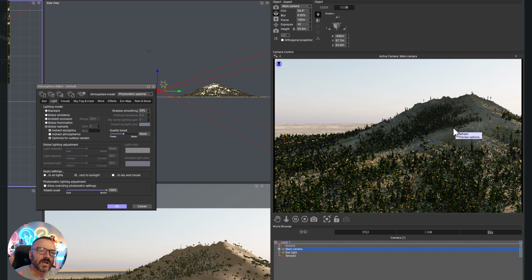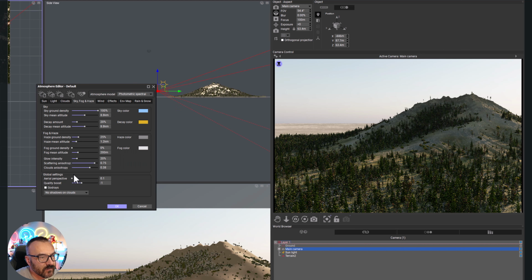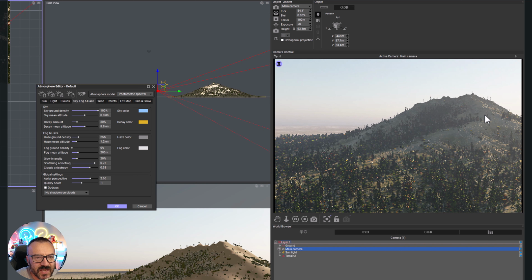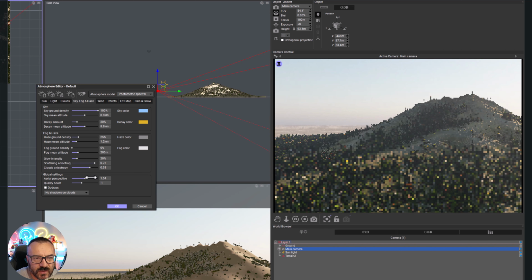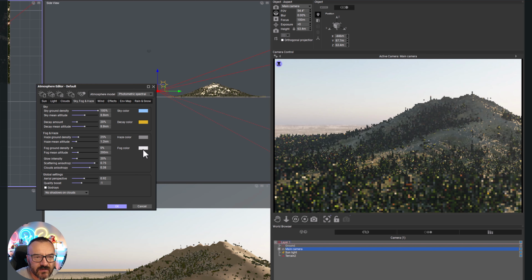Okay, now I want to add distance, and the best way to add distance is by haze, by desaturation, reducing the contrast, and reducing details. So this is the way we can go: sky fog, take aerial perspective, pop this maybe to about 2, 3, somewhere around there as a test, and you can see how much it adds this haze, maybe a little bit too much, so you can play with this around. I'll maybe drop it down. I think around haze maybe 0.9. I think this will add a better look.